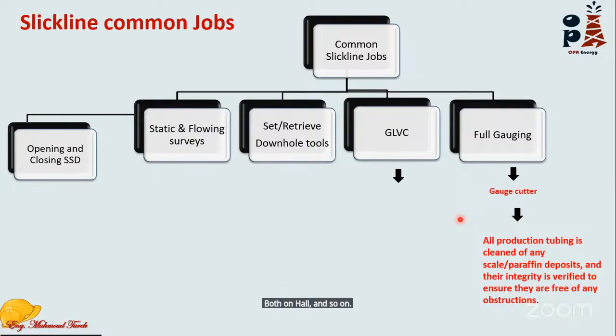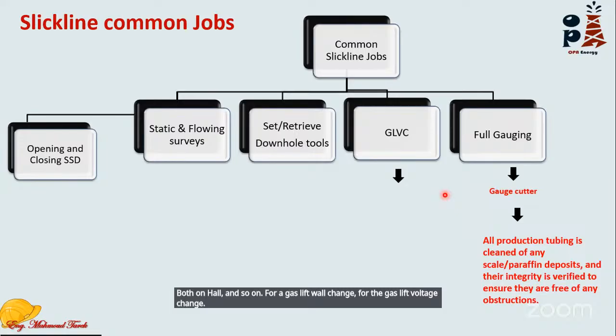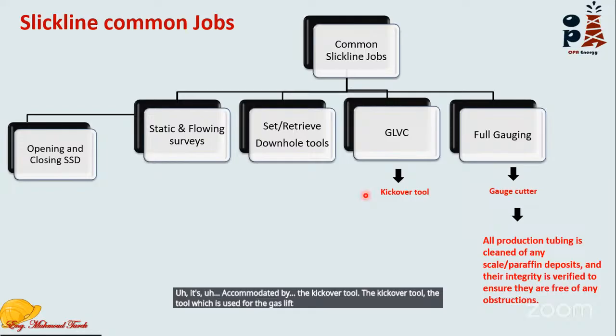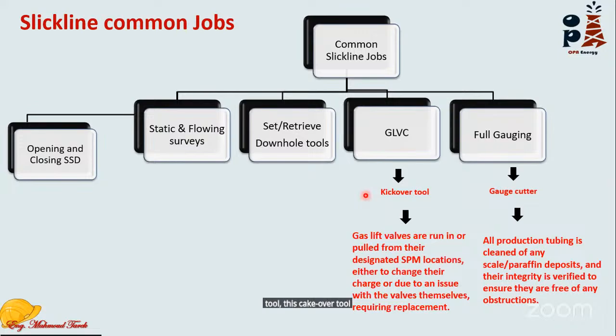For gas lift valve change, it's accommodated by the kickover tool. The tool which is used for the gas lift valve change is called a kickover tool. This kickover tool can be run attached to the PHA to change the gas lift valves, in case we have any reason to change our gas lift valves from the side pocket mandrels.